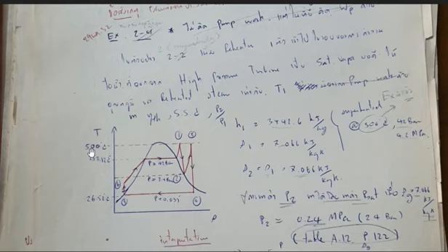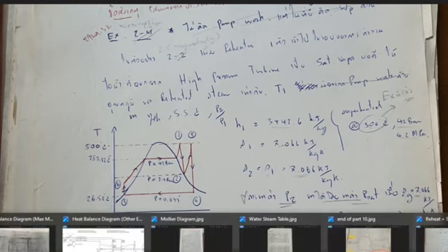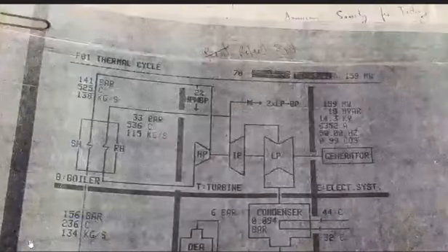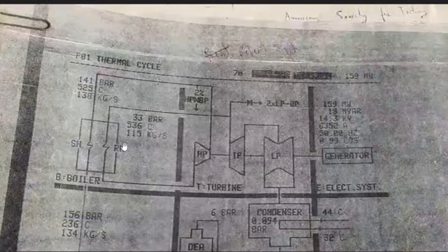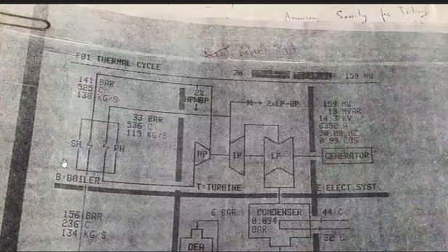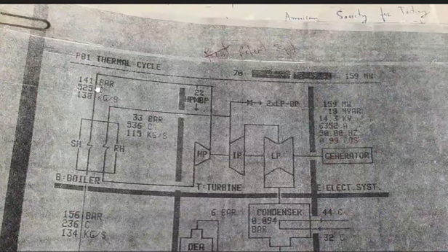For all the properties such as temperature and pressure at each point, we can measure them, and then we will use the known pressure and temperature to find entropy. And I will show you the values from a real thermal power plant. From this example, you can see that this is superheating. You can see the steam coming out of the boiler.